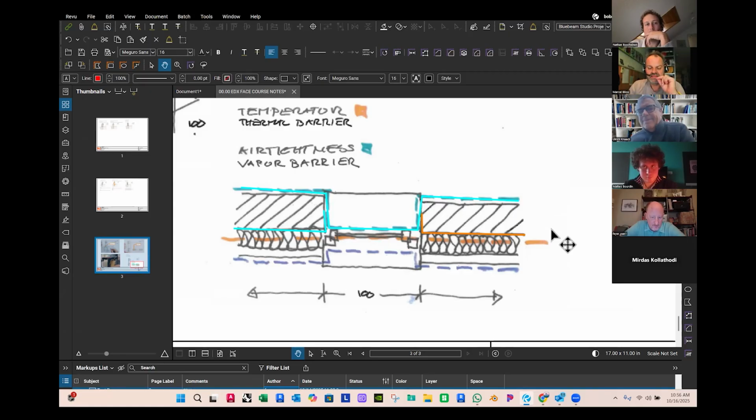Yeah, it totally depends on if you have, for instance, a window opening in a concrete wall. It's a total different application than a window opening in a skeleton wooden stick system where you have to use a film on the inside to make the entire structure vapor tight.